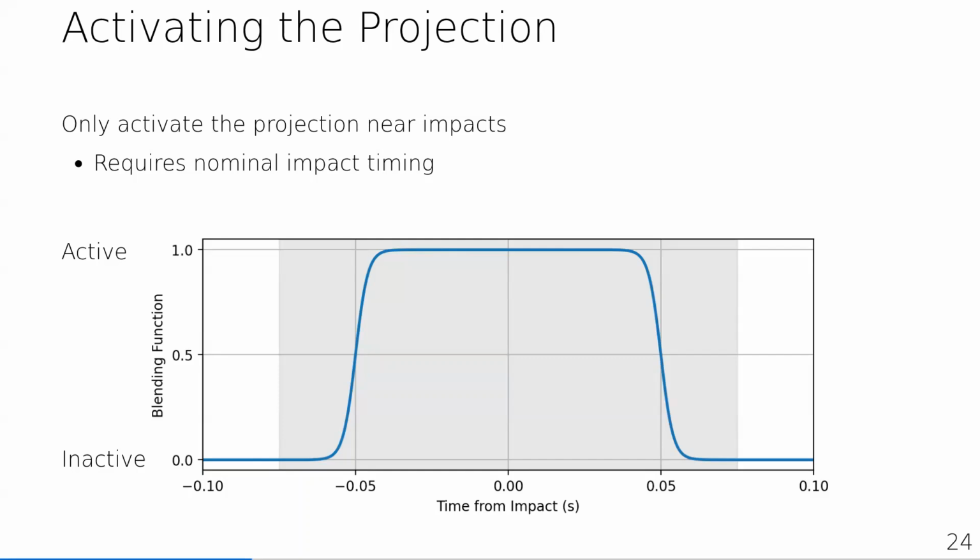Okay, so again, two questions. First is just clarifying that we do need to know the expected timing. So if we were to hit a rock that we never knew was there, could this be robust to it? The answer is no. We do need to know the anticipated contact timing, but also where. If we were to hit the knee on something, we're not doing anything about that. We still need the contact Jacobian. So the answer to that is no.